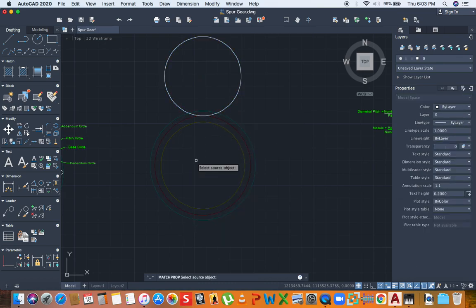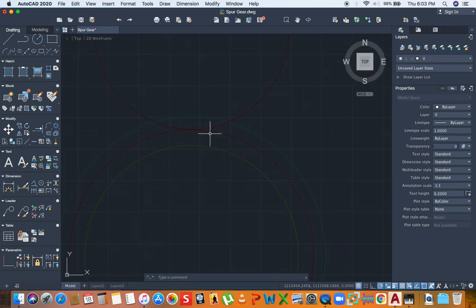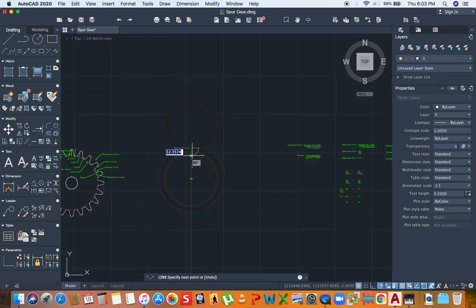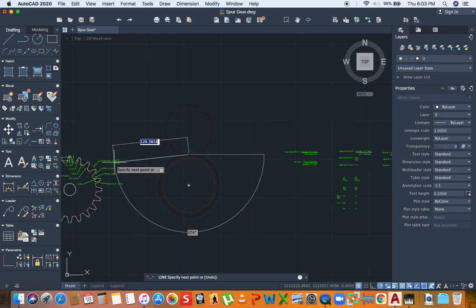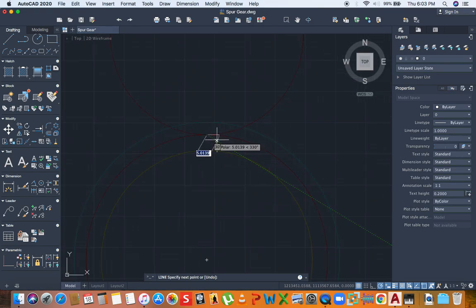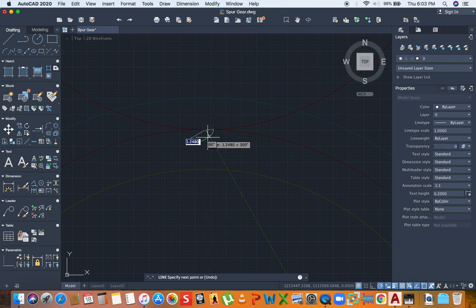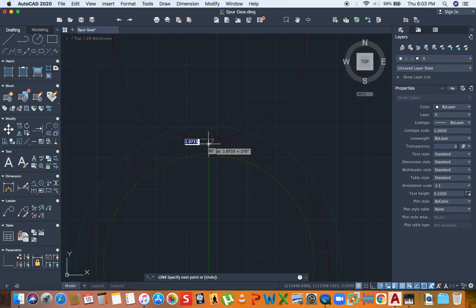Now, when two gears are working in unison and are meshing, both pitch circles must meet at this point that is referred to as the pitch point. I did not mention this point before. This is the point where the gear tooth from each gear will meet. Both teeth will meet here. They will touch here at the pitch point. They may touch at other points which you don't want, and that is if the backlash is 0. And I'll explain that further down the line.